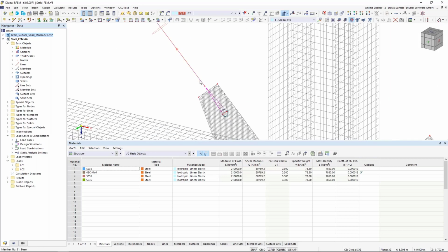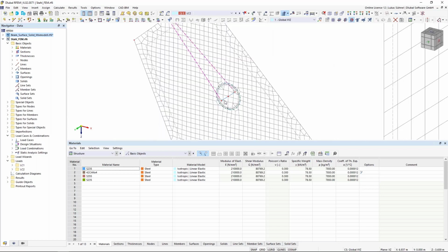So you can imagine if we have tension forces in that tension member, then the bolt will be moving to the, let's say, top left now, upwards, and we will get compression in that area. We will get tension on the back side of this plate, but since this surface will fail under tension, we have only forces on the left-hand side. And this is, let's say, a good feature to consider this connection between the bolt and the hole.